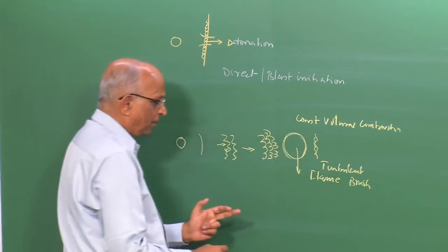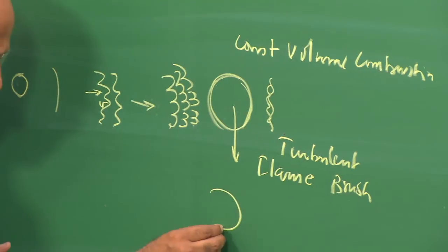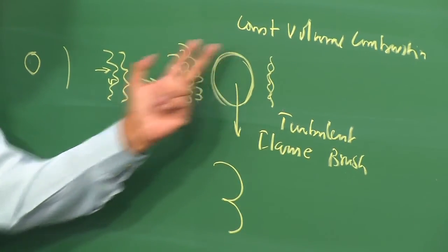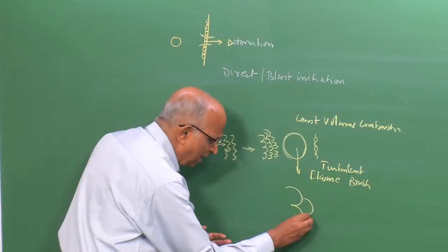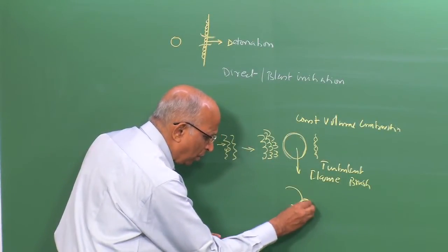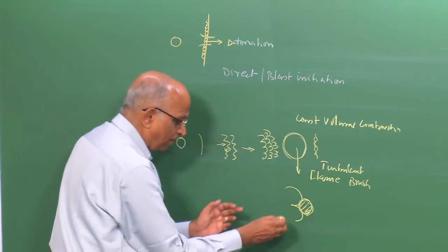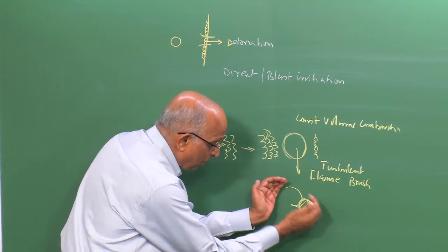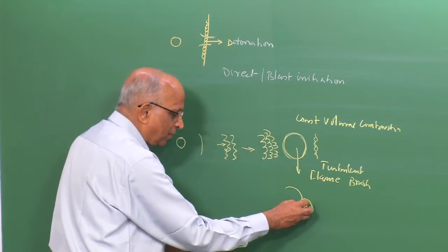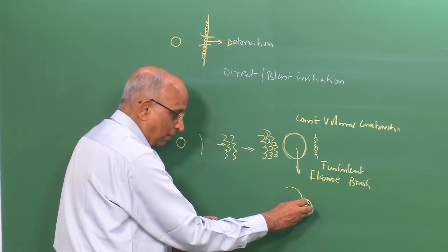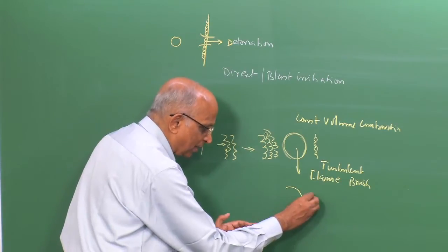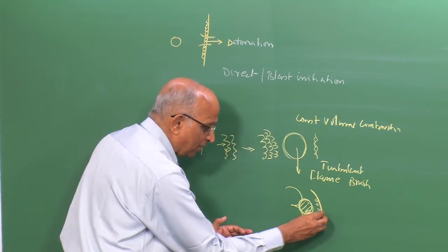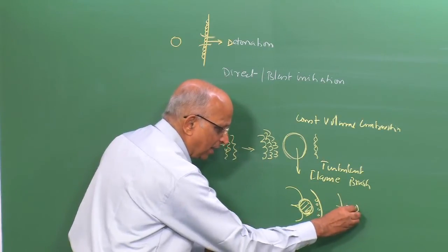because now it is able to form a shock wave, it can couple and form a detonation. Alternatively, if I have these wrinkled flames, the length scale also is somewhat larger in the intensity of turbulence, and supposing these wrinkled flames hold together some unburned gas mixture, and this unburned gas mixture is now being burned from the outside towards the inside, it collapses as something like an implosion takes place, and you form a shock wave. Behind this shock wave chemical reactions occur and you get a detonation.